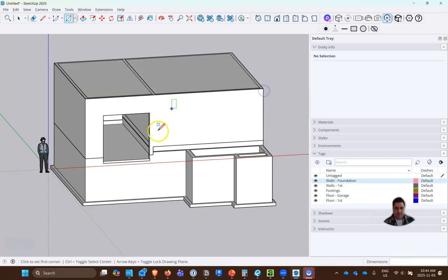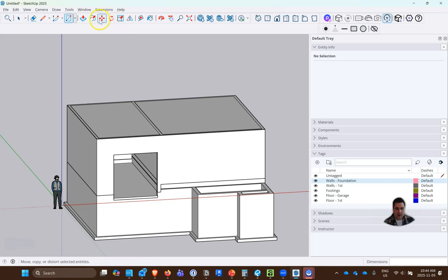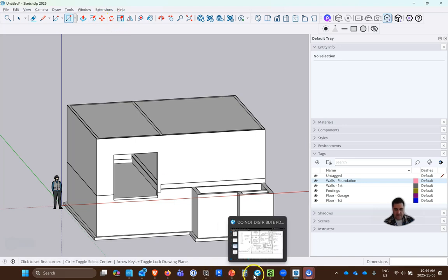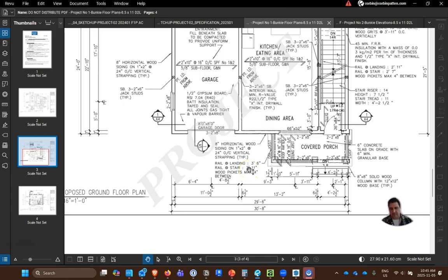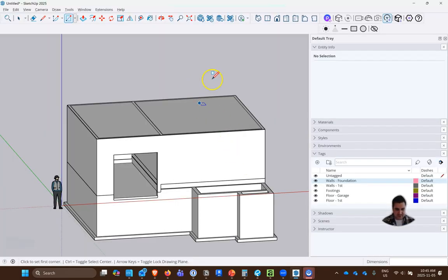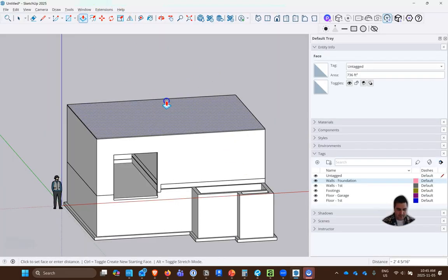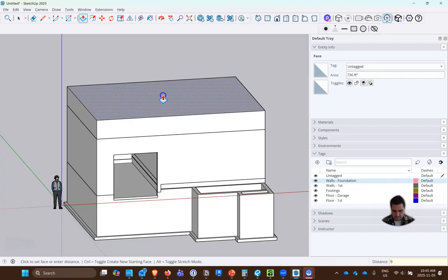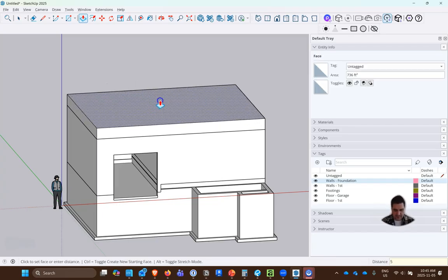And so we'll put our floor on there. Then just to verify, usually people will make the floor the same, but we're on our first floor, so we're seeing the structure above. In this case, we have the same 2x10s with 5/8 sheathing. So let's go up our 9 1/4, and then we'll go up our 5/8 again.